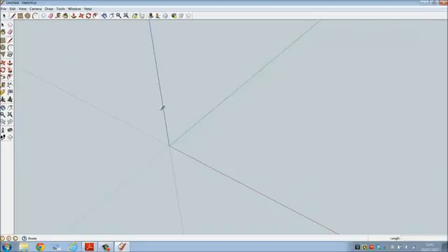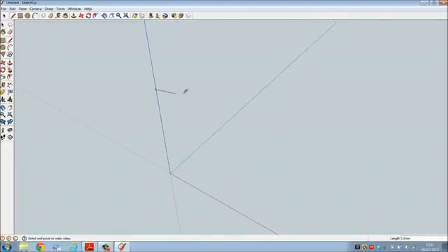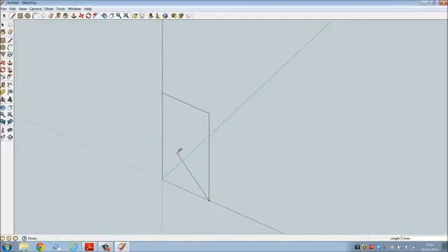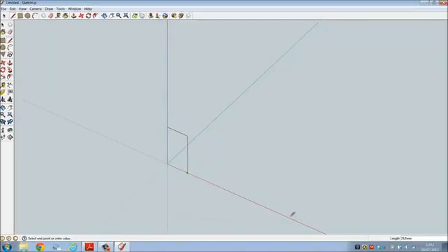So let's commence by drawing a line from the origin up along the blue axis of a distance of 10 millimeters. Now, as you can see, we are going to have to zoom in using the scroll wheel on the mouse, draw another line across parallel to the red axis of distance 5 and straight down of distance 10. Now, because that's in a perspective mode, we want to turn it into parallel projection for clarity. Draw a line from that endpoint along the red axis of a distance of 30 millimeters, line up, length of 3, cross length of 1.5, and connect as shown on screen.